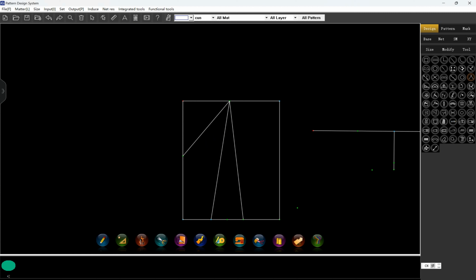And right click. You can also use the tool in the design mode: click the point here with the left button, put the smart pen here with the right button. As you can see, actually it's the same tool, but they have different operation steps. In the design mode, you click the left button and then the right button. But if you're using this tool, click the left button and click the left button. Pick the line with the left button using this tool. If you're using this in the design mode, it's left, right, and right click to finish. This is the single compass tool.